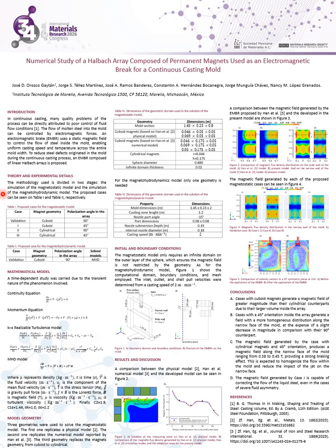It uses cuboid magnets, an angle of 90 degrees, and first, before going to the MHD model, we need to solve the fluid dynamics model. Then, once we have achieved a quasi-stable state, we import the magnetic field and solve the magnetohydrodynamic model.